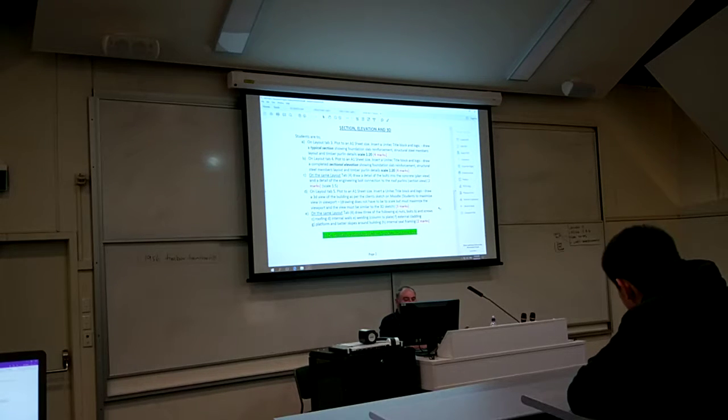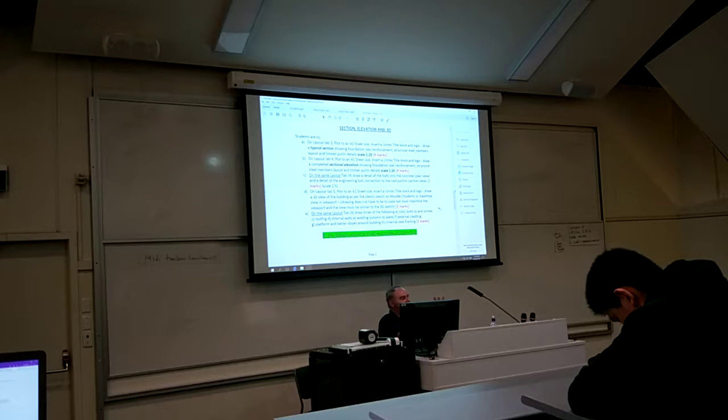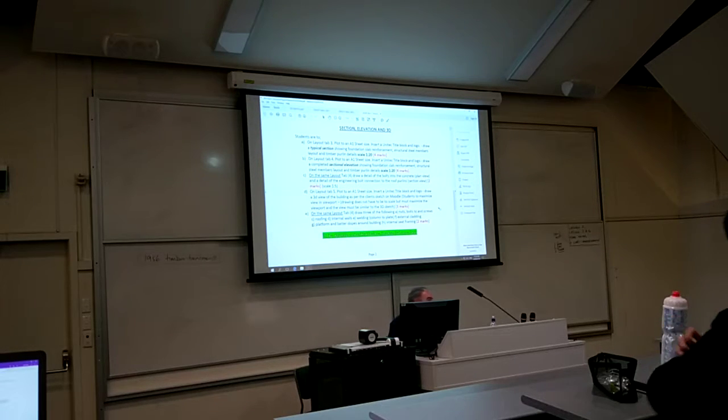I've been quite specific as to what I want. I want a plan view looking down on the steel plate, so you're going to have to come up with a plate size that works. You have to wait until week 2 for that. Also you're going to have to come up with a detail where the roof purlins are connected at the top there. Once you've drawn it, it should be relatively easy to detail it. Things I'm looking for in the detailing: the welding symbol, the distances to the bolts, the overall size, and the hole size for the bolts that you're putting in.